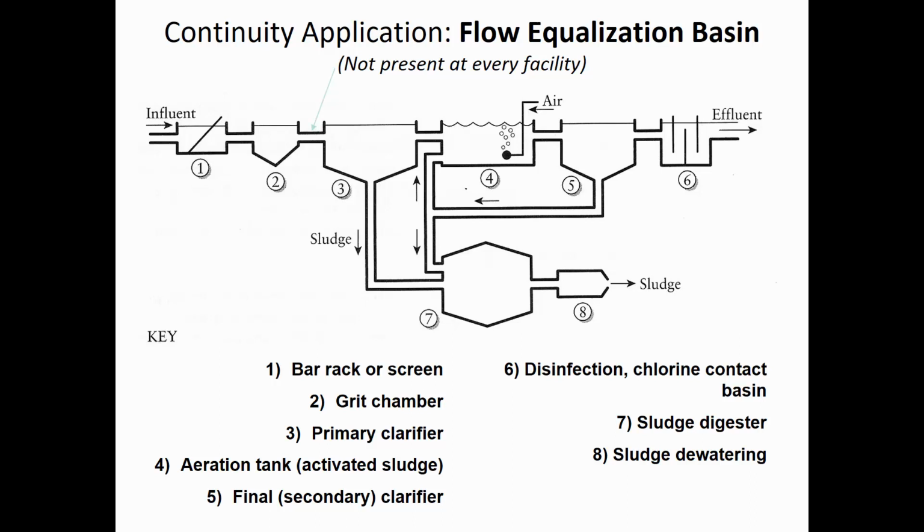And so this treatment plant has a lot of water coming to it sometimes and just a trickle at others. And since it's a biological process, the microorganisms that do the purifying of the water can't turn on and off like a light switch. They react actually very slowly, and so it's much better from an efficiency standpoint if they always have a more constant flow rate. And so there has to be a storage tank inside of a water treatment facility if you want to provide that attenuated flow.